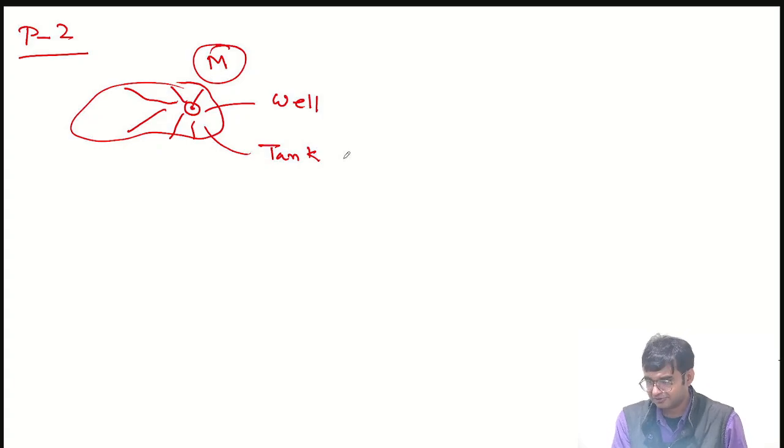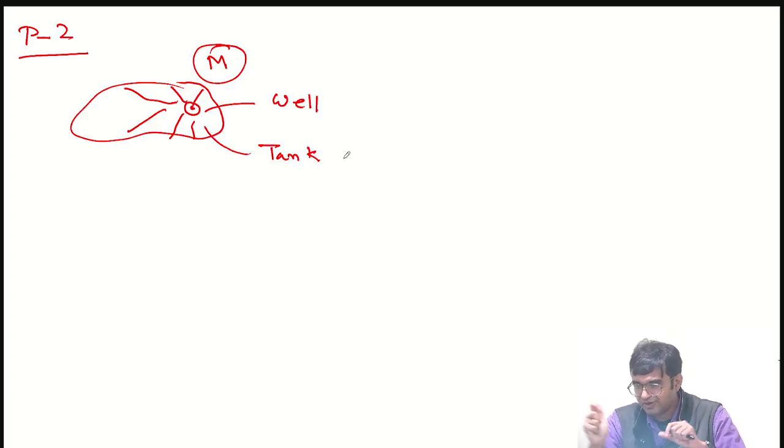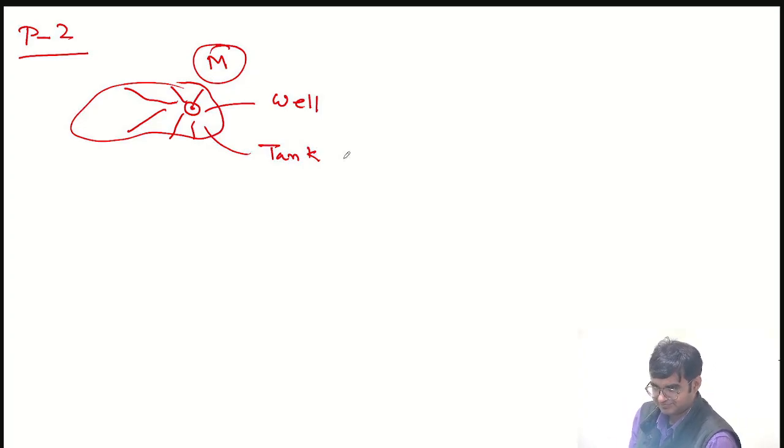If that was series, this has to be parallel. But this is also known as redundant, because you have redundancies. Even if one fails, you have backups, redundancy, right? So this is known as a parallel system. Now the series and parallel systems are actually two extremes. Real systems are neither series nor parallel, they are mixed. Some portion might be series, some portion might be parallel, right? And so these two are kind of extremes.